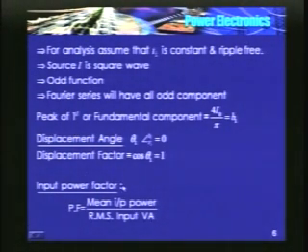What is the input power factor? It is defined as mean input power divided by RMS input VA. We know that it is only the fundamental component of the input voltage and the input current that are responsible for power transfer.